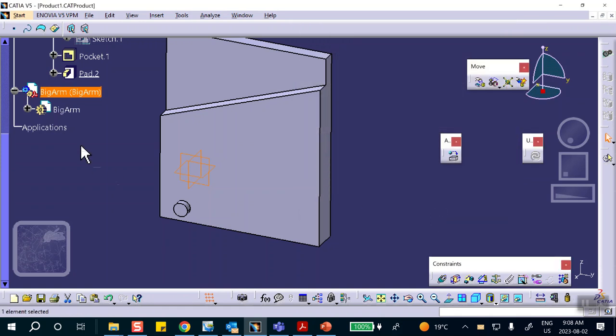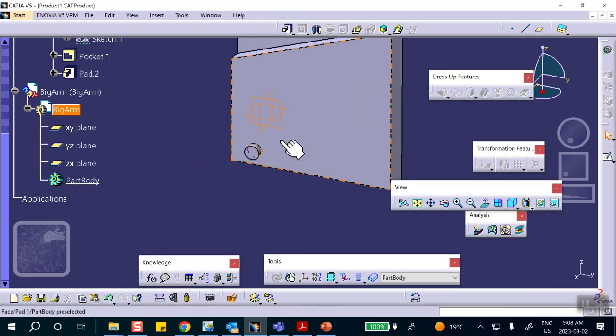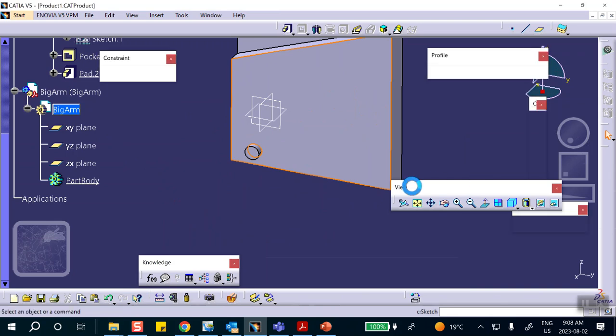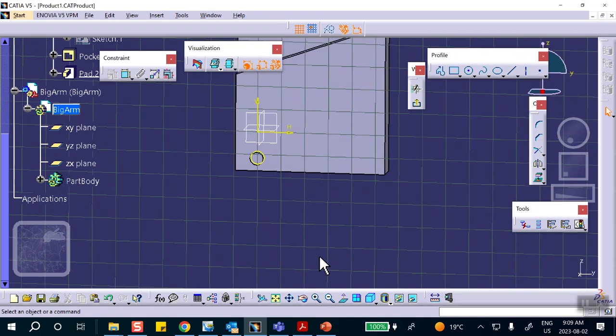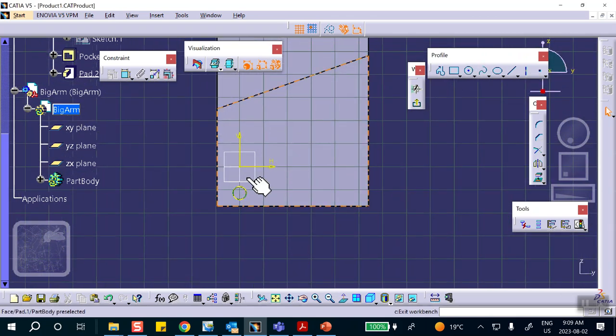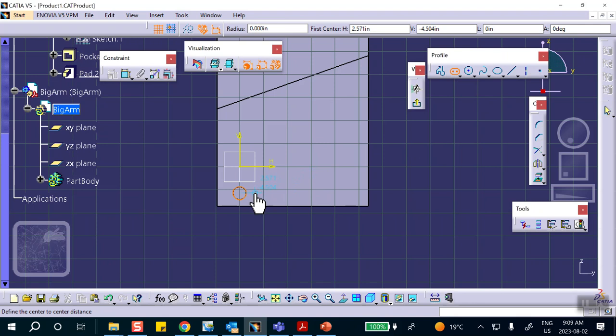Let's make it. So let me do that. On that face, I will sketch. Why don't I project that circle? There. Normal view. Now let's do that. For example, the rectangular piece. Okay, so I'll do the elongated hole, and I'll clean it up in a minute.